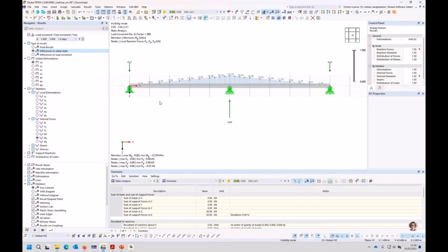This means that, for example, due to the consideration of creeping, there is not only a simple reduction of stiffness, like it could also be done in a more simple way to consider creep. Here there are used elements consisting of an elastic and viscoelastic part. So elastic part for the load, if I apply load, and viscoelastic part to consider these long-term effects like here creeping.